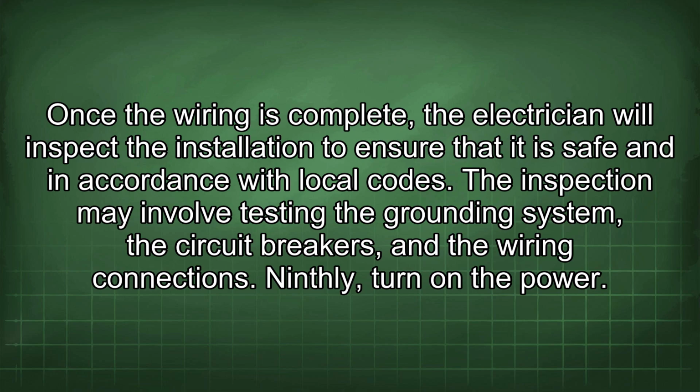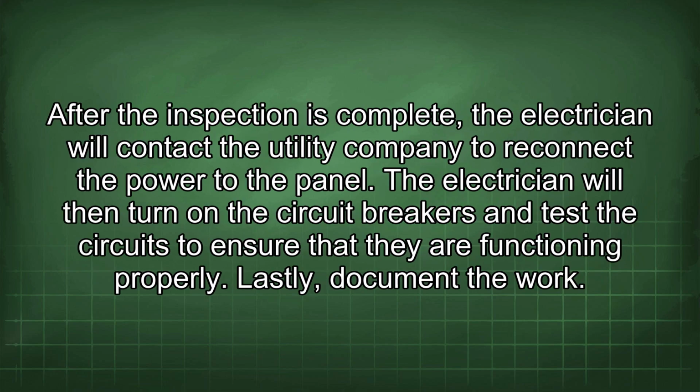Ninthly, turn on the power. After the inspection is complete, the electrician will contact the utility company to reconnect the power to the panel. The electrician will then turn on the circuit breakers and test the circuits to ensure that they are functioning properly.